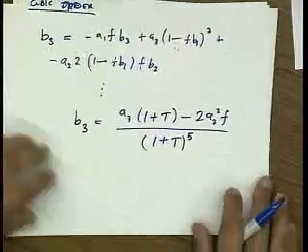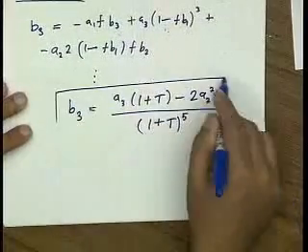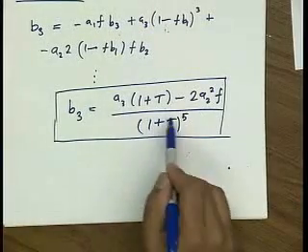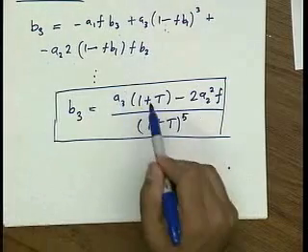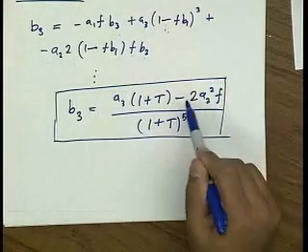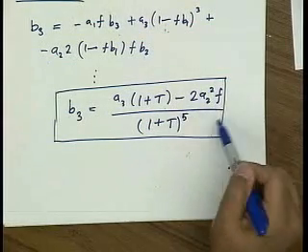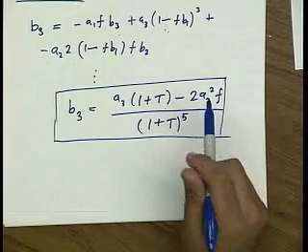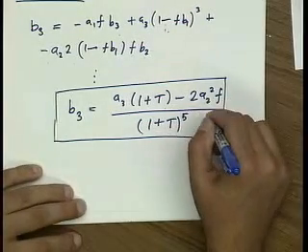Okay? So there's some good news and there's a little bit of bad news. The good news is that compared to A3, we can see that by 1 plus loop gain to the 4th power, we get a reduction. The bad news is this term. Because this term actually introduces cubic order distortion in a system where you didn't even have it to begin with. This is called the second order interaction term.